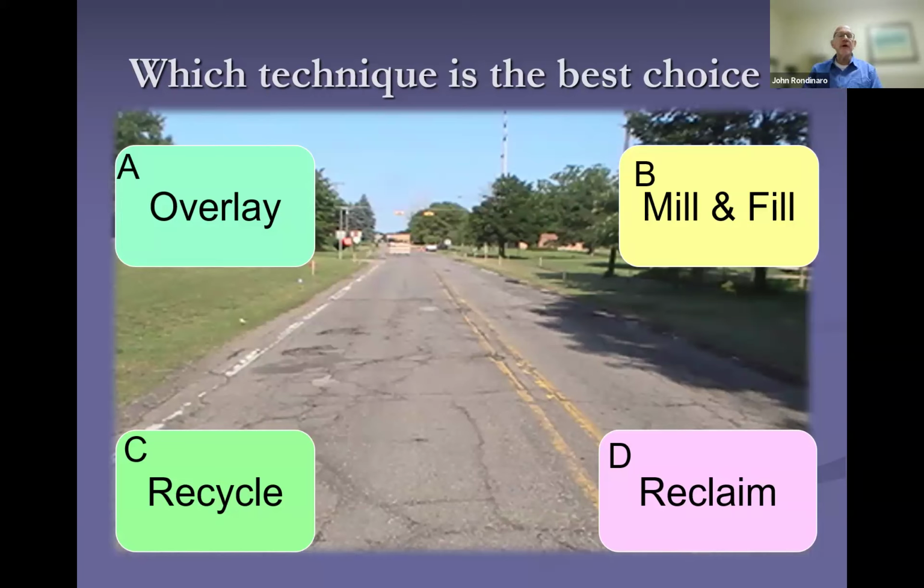So you've got to look at your drainage, you've got to look at how thick your asphalt section is, you've got to look at anything else that might constrain you, matching up to your intersections, matching up to any driveways. All those kinds of things have to be considered when you're thinking about your treatments. But good range of answers, and everybody's right.